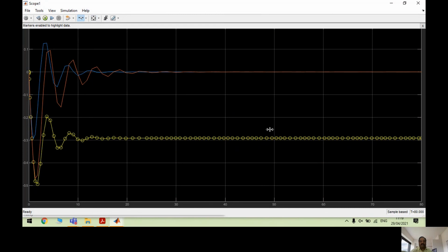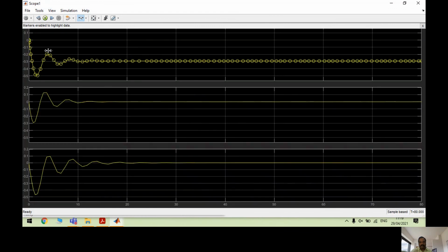Yeah. You carefully see. The bottom one, the yellow one, is the initial one, which is generally, okay, for your sake, I'll make it as 3. See, the top one is without any countering. It was just only demand. Because of the demand, there was a change in frequency. The second case is countered by manual power setting. The third case is countered by my integral controller. See, if you can see, the integral controller is also giving a steady state value of 0.